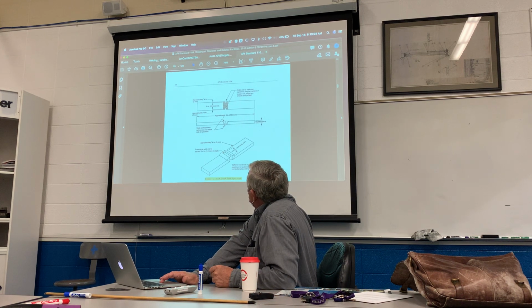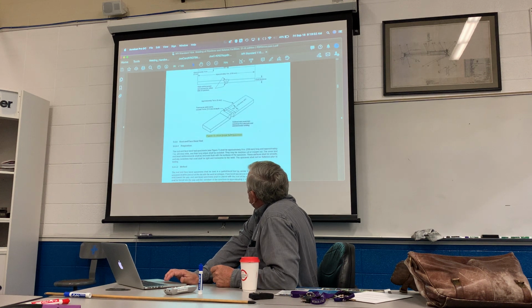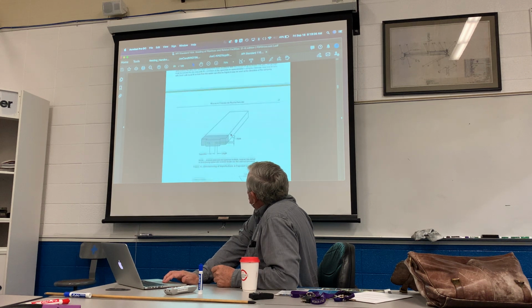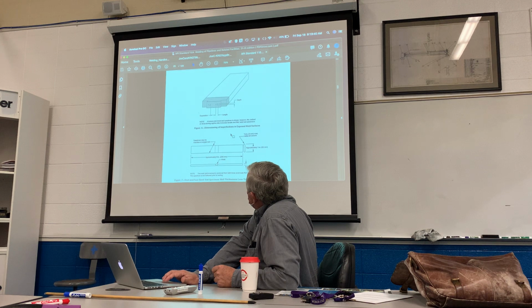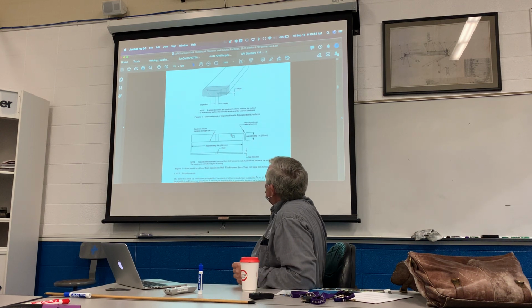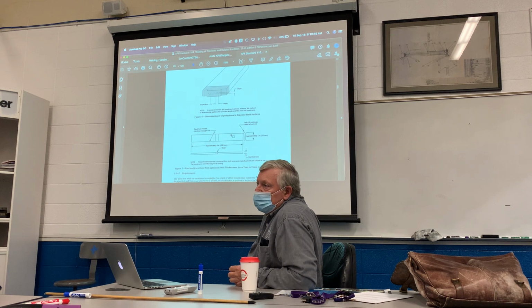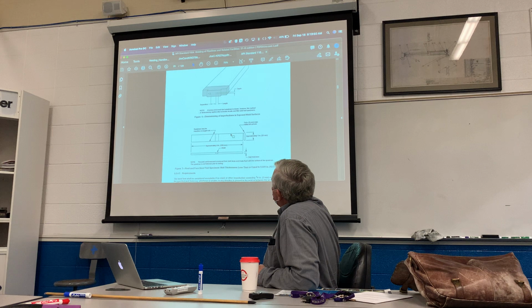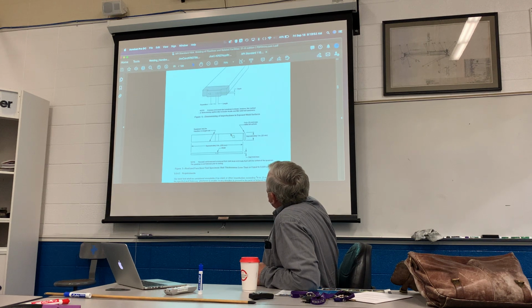Notice they're 9 inches long as well. We will see when we look at the branch, you'll see a little bit of difference in coupon. This is the dimensioning for exposed weld surfaces and discontinuities found in nick breaks. The general rule is the depth, the length, and the distance apart.